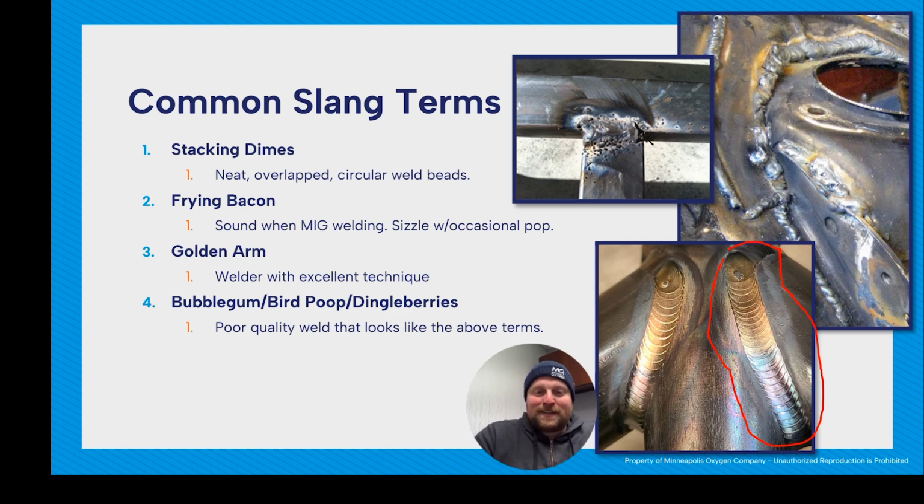But just because a weld looks like that does not mean that what's underneath is good. A good surface looking weld probably means your weld is good all the way through. But this is why when we do inspections, we'll do different sorts of non-destructive testing and destructive testing, because you can cover up a poor quality weld with a great looking cover pass. It is possible. So that's just for appearance. That's not about our structural weld.